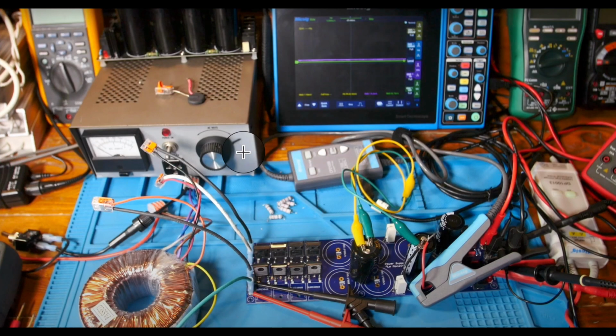Alright guys, this is from that video that I did before. Links down below again. What we have is the mixed signal scope. We're going to look at waveforms. I'm using this power supply board that I've built up since then. I have a bridge rectifier over here on the left, 4 diodes. There's actually 8, 4 on each side. There are 4 capacitors on this side, 4 on that side. The first one's installed up here in the left corner.